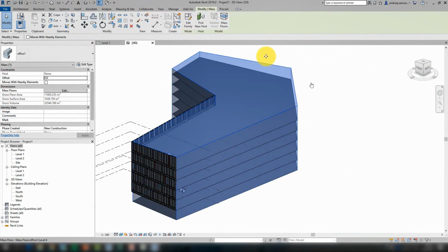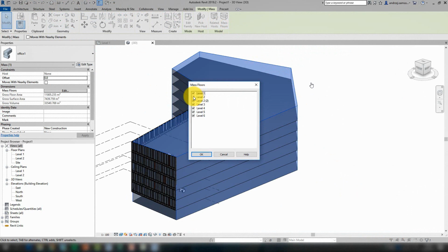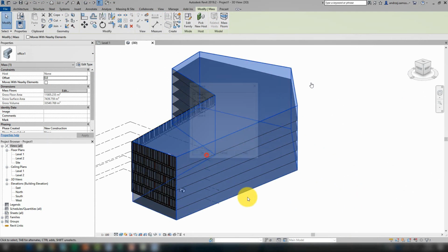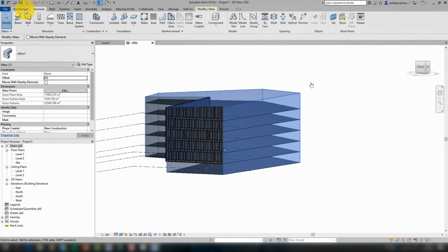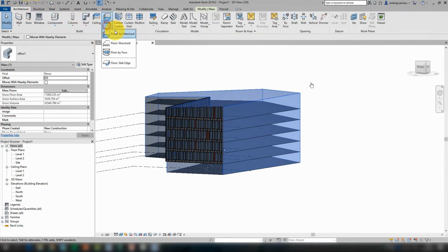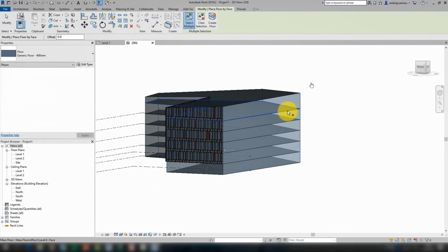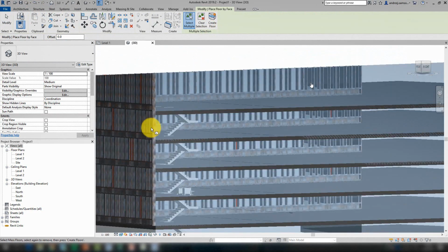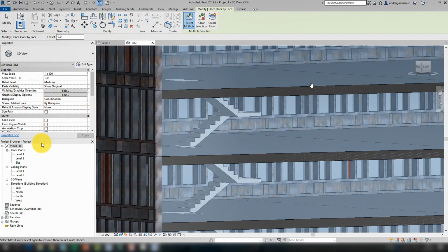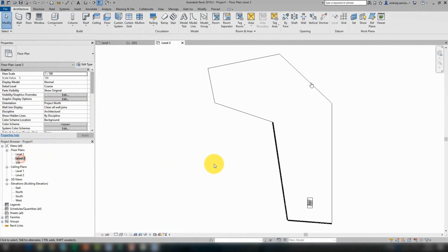But nevertheless, I can still simply delete something, or there's the possibility of slight modification. Here, I can also again start using this mass, this volumetrics that came from Formit to Revit, and create some regular Revit elements based on that.